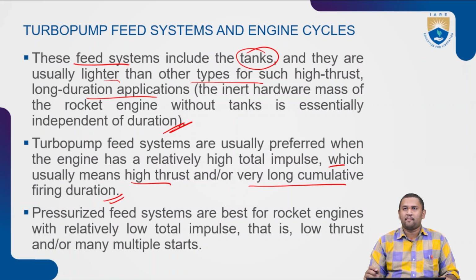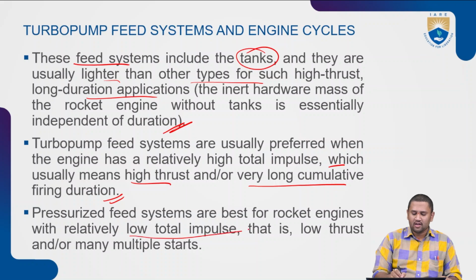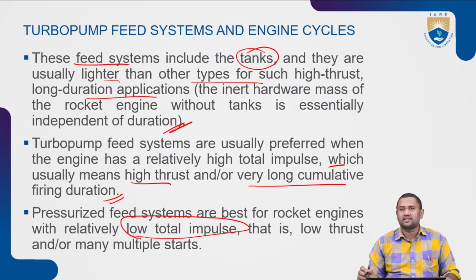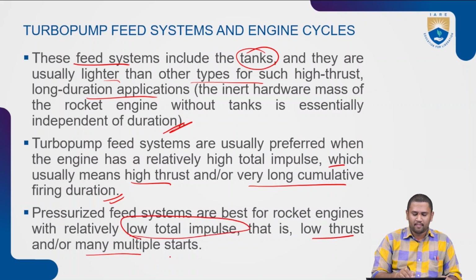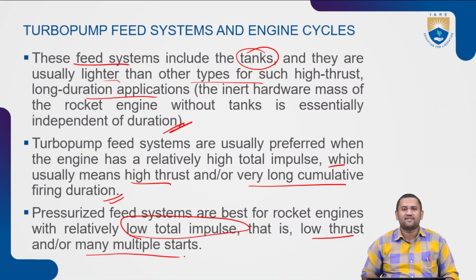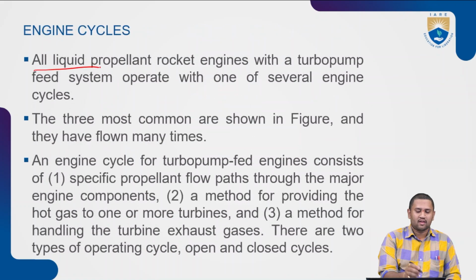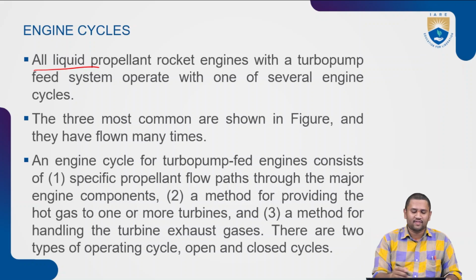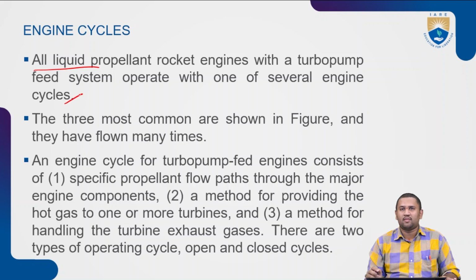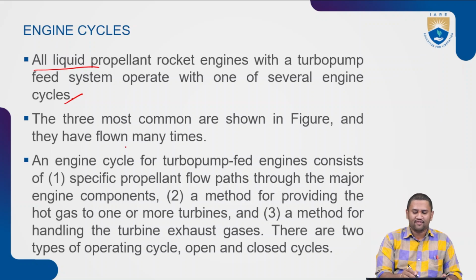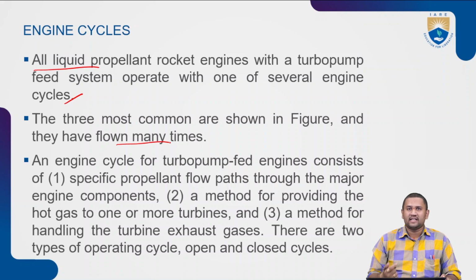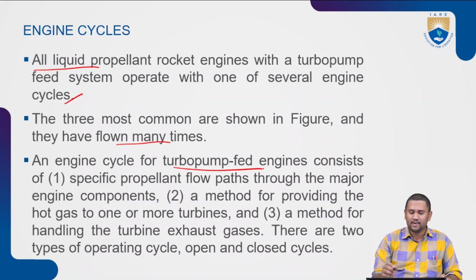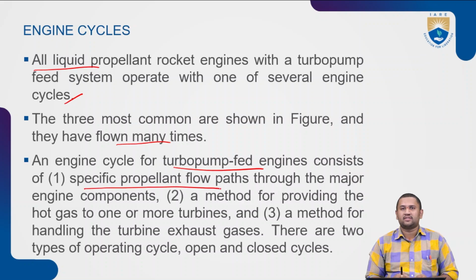Pressurized feed systems are best for rocket engines which have relatively low impulse, low thrust, or many starts. All liquid propellants with the turbopump feed system operate on one of several cycles, and the three most common, which have flown many times, are shown in the figure that we will be discussing next.